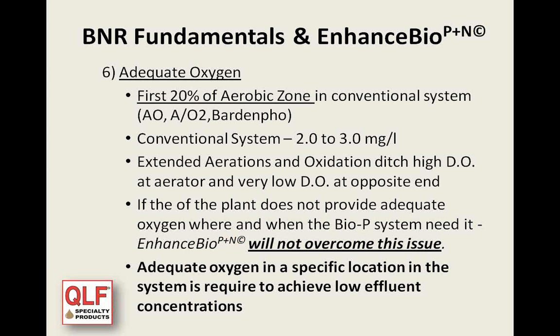And adequate oxygen. With a conventional system, AO, A2O, and Bardenpho, you look at the first aerobic zone, and the DO should be between 2 and 3 milligrams per liter. In extended aeration and oxidation ditch, high DO at the aerator and very low DO at the opposite end. Again, if you don't provide enough oxygen, we're not going to overcome that issue with our product.